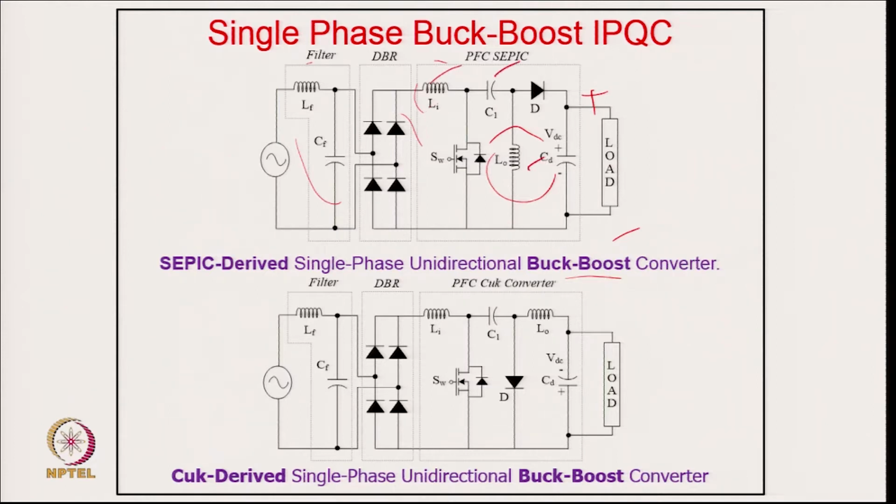So now you can think about the total designs corresponding to DCM and CCM, maybe 2 to the power 3, the 8 designs. You can have all DCM, you can have all CCM, these are the two exclusive designs, but you can also have only one component with discontinuous operation: either the inductor will have discontinuous current or continuous current. Similarly, the capacitor can have a discontinuous voltage or a continuous voltage across it. So like this you have 2 to the power 3 designs, and you select the best design that is acceptable to you for a particular application.